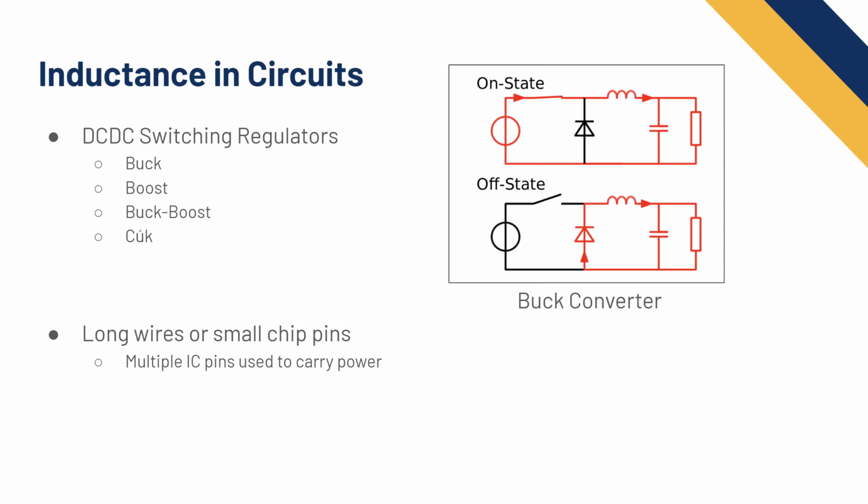All right, I know there's a lot more that we can explain about how this works. I just wanted to give you a general idea that this is possible, that you can divide voltage. And then the boost can multiply voltage if you rearrange the components in here. Mainly rotate the diode and swap the inductor and switch.